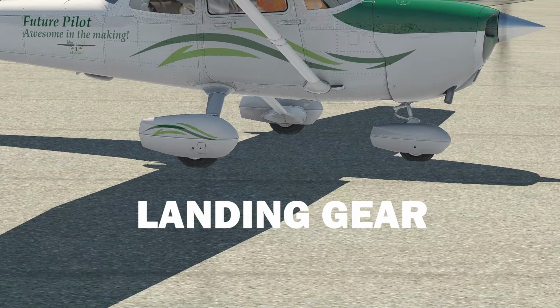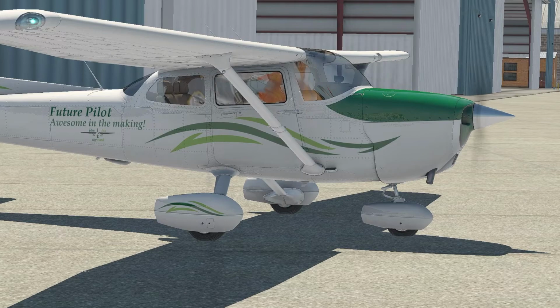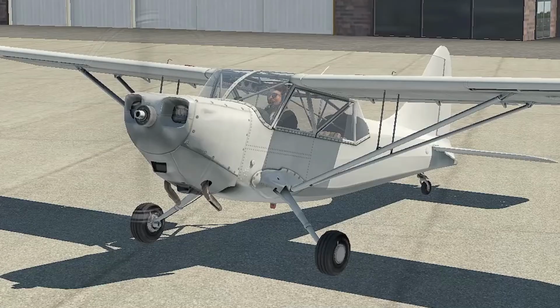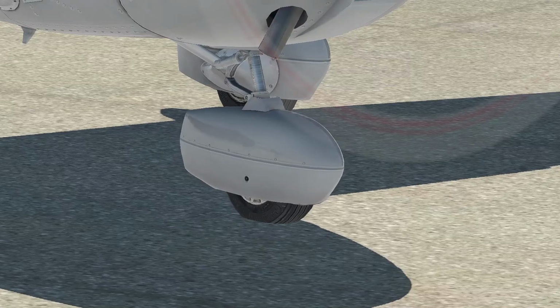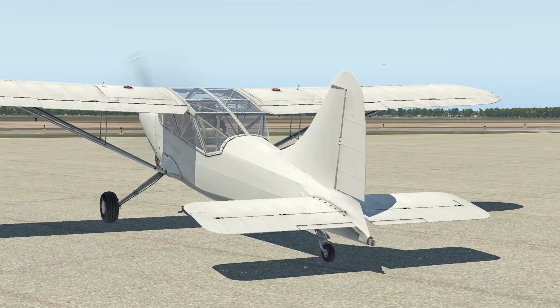Most airplanes rely on wheels to land. Some use skis or floats. There are two main types of landing gear configurations: tricycle and conventional, otherwise known as tail draggers. Tricycle has 3 wheels, 2 under the wing and 1 under the nose, which is also used for steering. Tail draggers have 2 to 3 wheels, two under the wings, and a wheel or a skid under the tail.